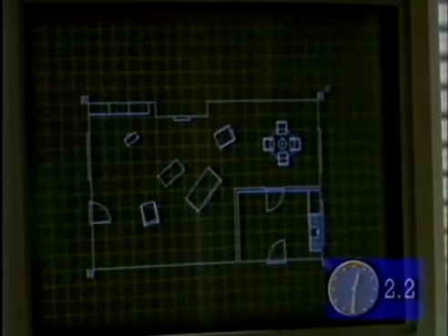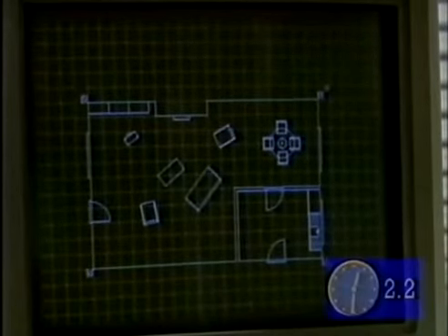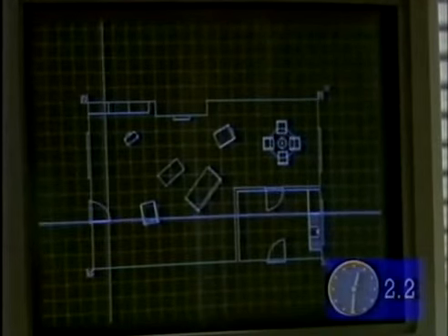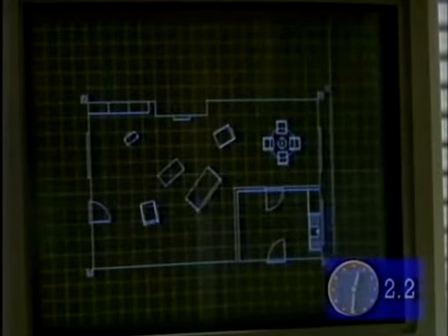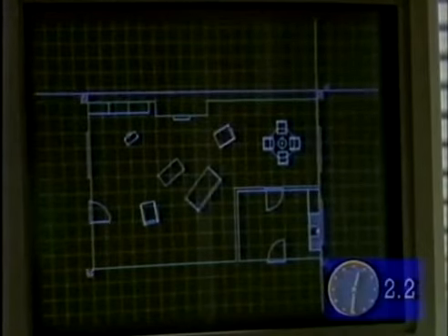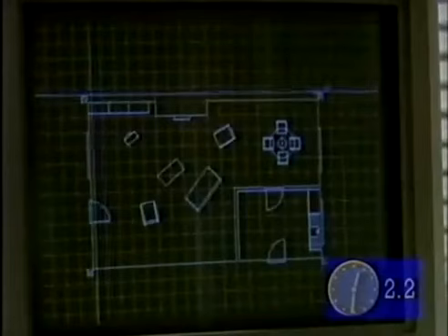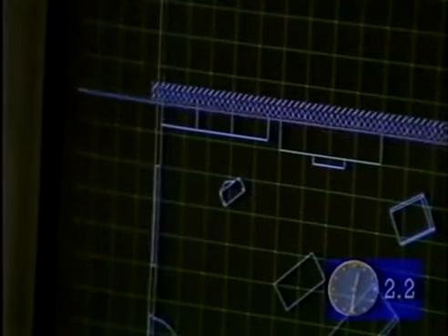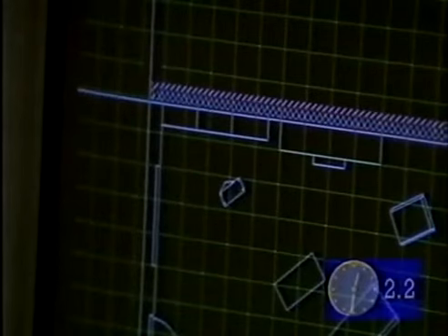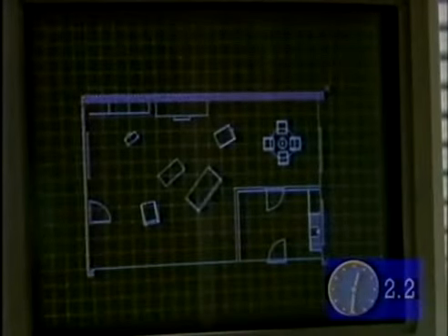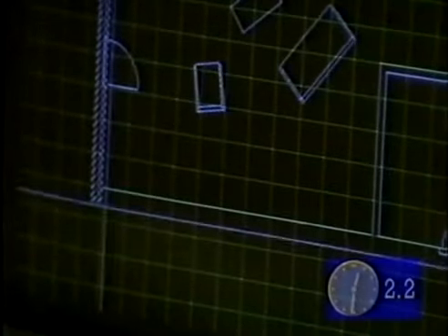As I say, what we now need to do is pull in another symbol which is going to stretch walls from one corner unit to another corner unit. So again, selecting it from the menu, all I need to do now is point to one of the corners, like so, and it snaps to that symbol, and then the other side of the symbol. So this is a kind of elastic symbol whose length is defined by those two points, those two cursor positions, to make a continuous run of brick wall.